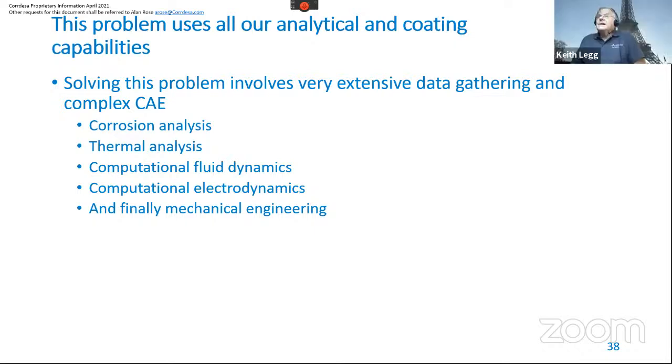You can anodize a bit more over the top, but you're not going to anodize the full thickness. So you'll know at the end of the repair how much total current was delivered, and you'll know how much acid you used and everything. You have all that information, and of course you can make some measurements as well to check thickness.